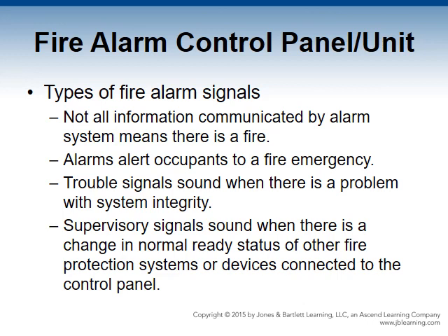By electronically supervising the valve, an immediate investigation can be initiated if there's a problem. The signal will use the same constant tone and light as the trouble signal. It is not an alarm signal, and fire department response should not be necessary. Any supervisory signal should be investigated in a timely manner and should be followed up with and investigated by a qualified service technician.